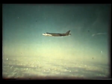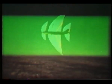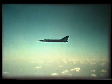So when considering airflow, it's convenient to divide flying speeds into 3 ranges. The subsonic speed range, covering all speeds at which the flow everywhere around the aircraft is subsonic. The transonic range, covering all speeds at which the airflow is mixed, part subsonic, part supersonic. That is, from M-crit to about Mach 1.3. And the supersonic range, covering speeds at which the main flow everywhere is supersonic.